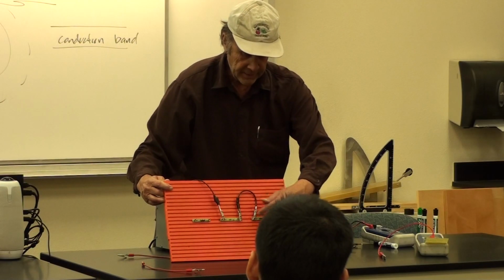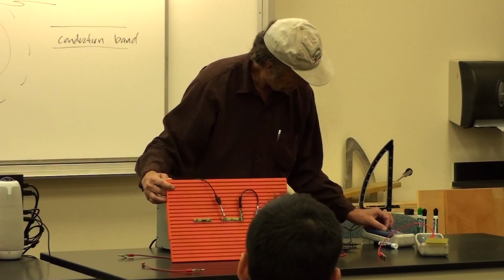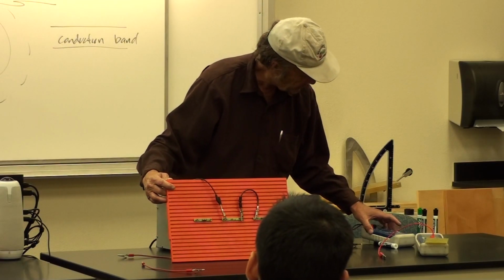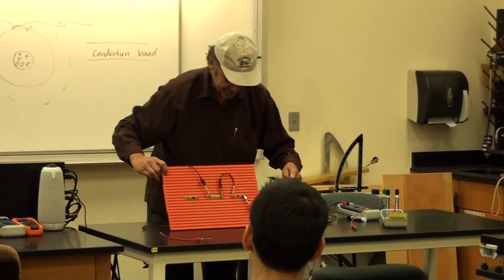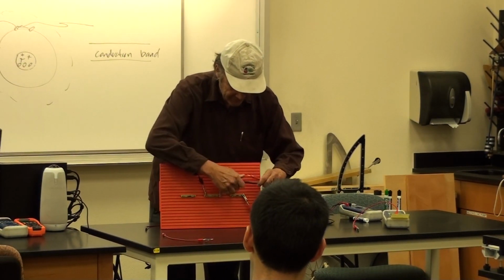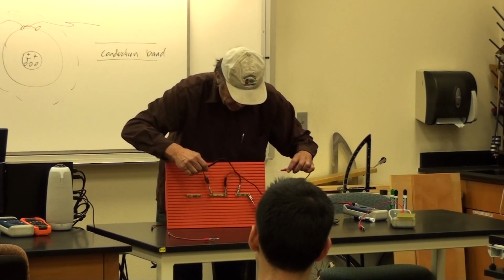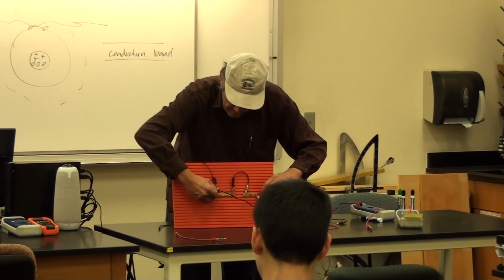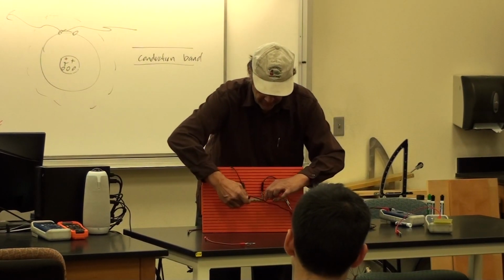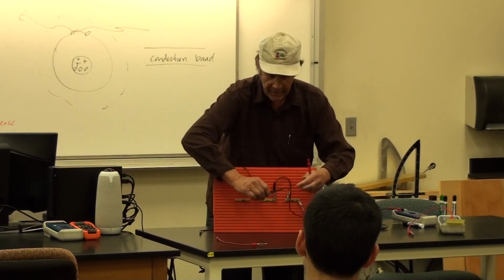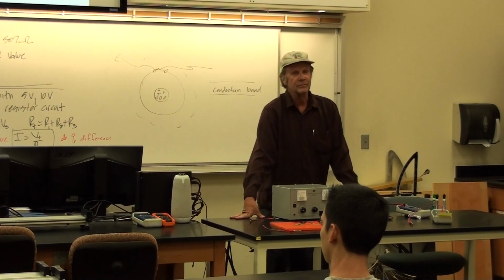So we're just going in, across, across, across, and this is the easy part, the part that you don't have to worry about blowing out any fuses. There is a part where you have to worry about blowing out fuses, but this isn't that part. So then you just go across here, you go across here, and then you can go across here. Like this. That's your total. This is across 1. This is across 2. And you don't even care whether you got a positive or negative, because if a measure's negative, it just means you guessed wrong.